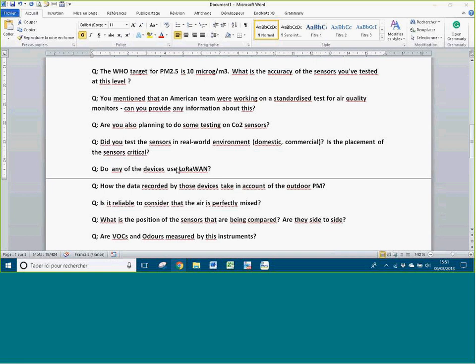So maybe you might have a couple of sensors in a home if you wanted to do this, or in an office space, if it's a large open plan office, you might have more than one or two, and you can think about maybe critical locations. Because we know that we get a lot of particles from cooking, probably one would be the kitchen. And the other sources of particles are generally people's activities while they're awake and so on. So maybe another sensor in the living space if you wanted to go to a multiple sensor approach. That probably seems like a good idea, particularly in a larger home or larger office space.